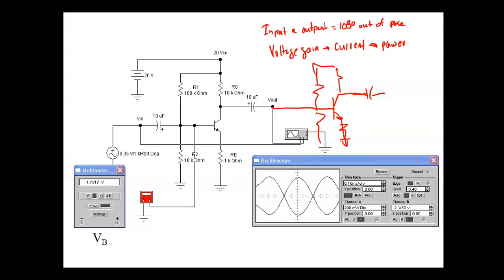But technically, it's an opposition to an AC signal in a circuit that has both reactive and resistive devices. A lot of people in AC talk about the opposition of impedance anyway. They don't use resistance at all. And when we try to get maximum transfer between systems, we're trying to match the impedance between them as closely as possible.